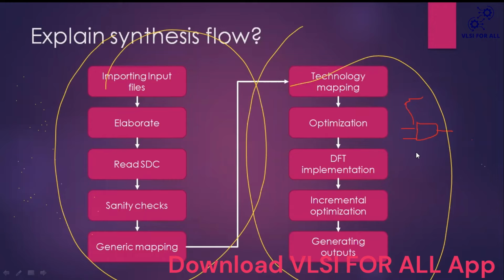Like, I have 100 flip flops in the design. Are these 100 flip flops working properly or not? How can we check after it is manufactured? For that, they will convert normal flip flops to scannable flip flops. What are scannable flip flops? They have two extra inputs, scan input and scan enable.